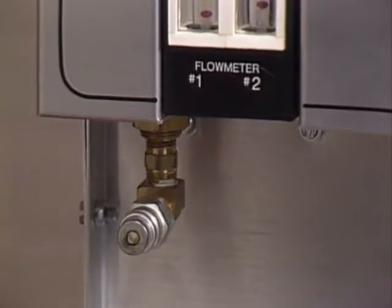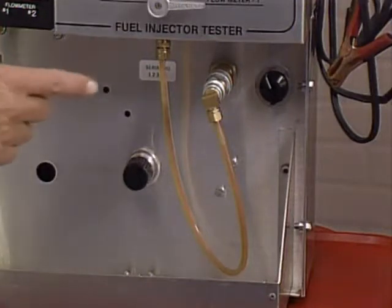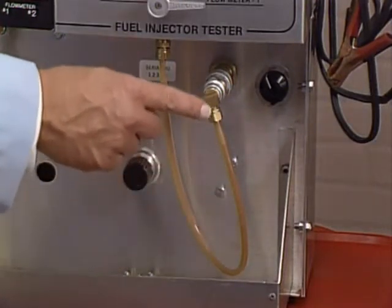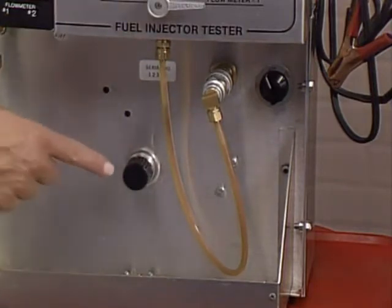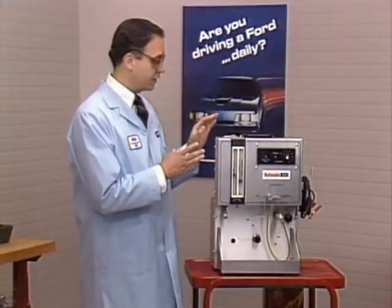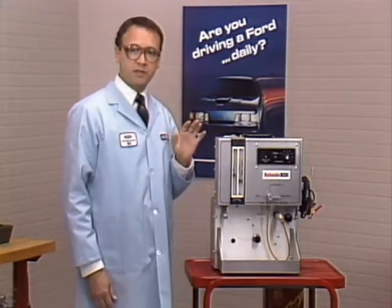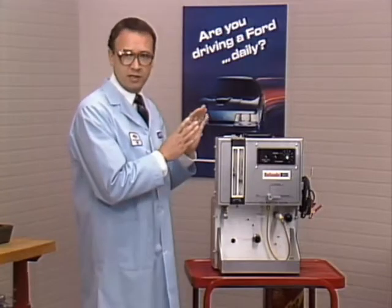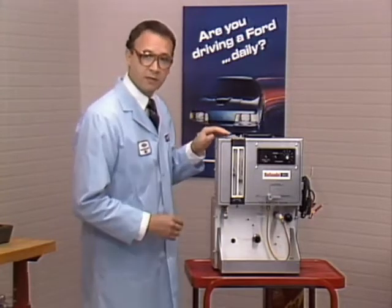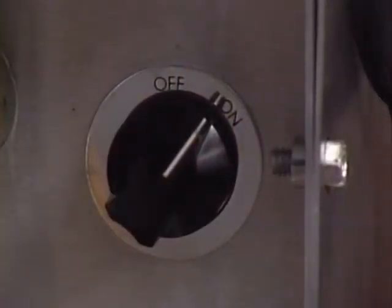From this outlet, fuel flows to the injectors that are being tested. The other fittings on the tester cleaner are the fuel return fittings connected by the return line. This black knob is the fuel regulator. It's used to adjust the fuel pressure supplied by the tester cleaner as described in the operating instructions. Now the last item on this side of the tester cleaner is the manual shutoff valve, right here. When the manual shutoff valve is in the off position, fuel does not recirculate inside the tester cleaner. With the valve in the on position, fuel recirculates with the tester cleaner on.